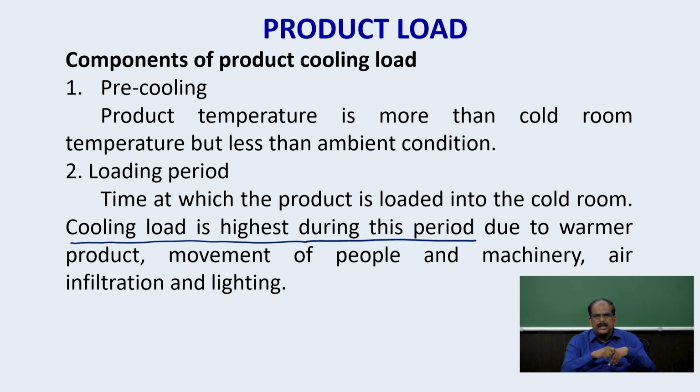Load due to infiltration, leakage of air through the gaps or through the holes, etc. And the lighting will be there, so the lighting load also will be adding to the total cooling load. And if there is machinery, it will be using some motors, so the equipment load also will come into picture. So the cooling load is maximum, especially during the loading period.